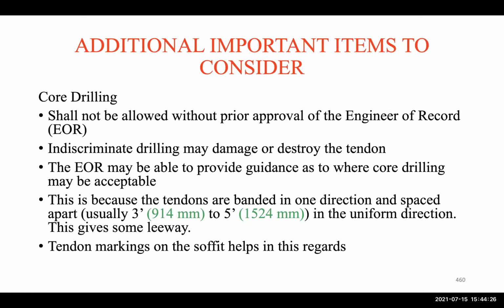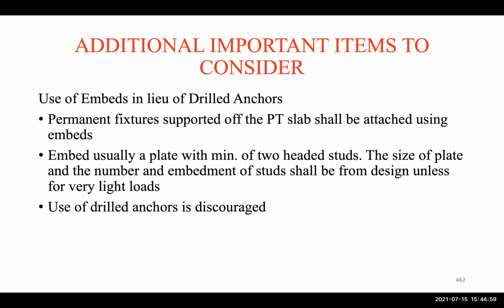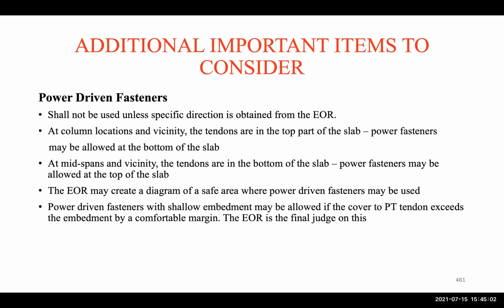Core drilling, so the same thing. Any core drilling within the slab has to be checked with the engineer of record, and the engineer of record will give the direction on how to do that. Okay. So, for example, the tendons are banded in one direction and spaced apart 3 feet to 5 feet typically in a uniform direction. So this gives some idea of where cores can be taken, but again, it has to be consulted with the structural engineer, the engineer of record.